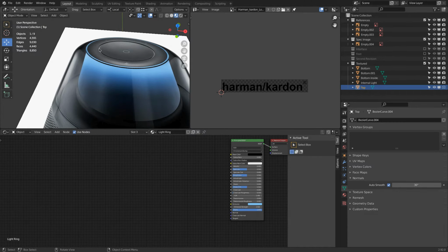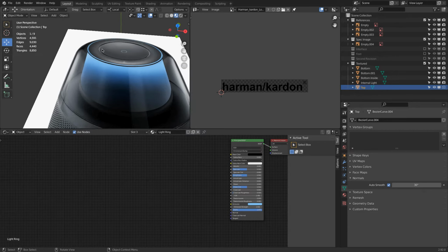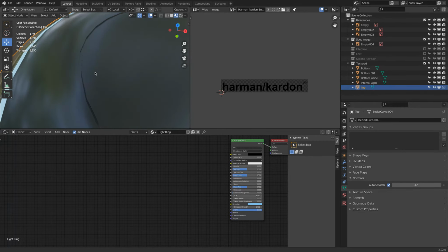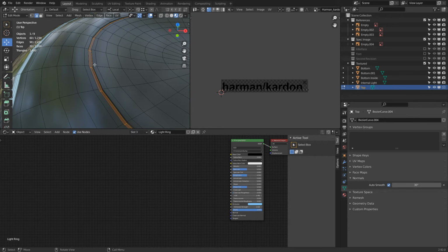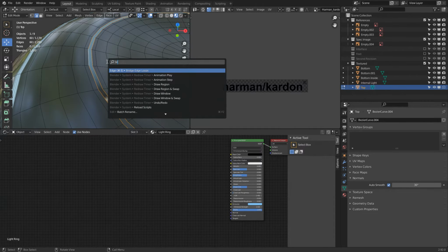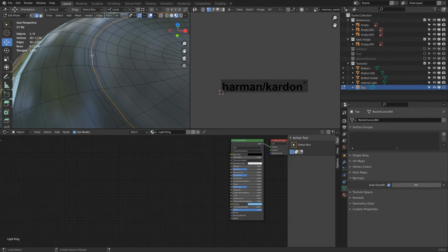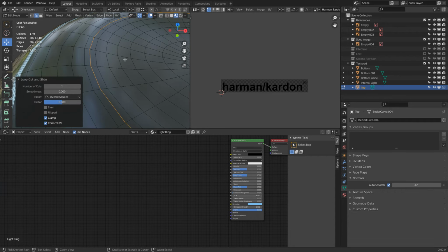Okay, you see it looks like there's some sort of other material behind it. Our gap here actually is way too small. So how do we make this bigger? Easiest thing, we delete this, go to edge select, alt click this, shift alt click this, and then press spacebar, type in bridge. So we bridge it, click this, alt X, dissolve edge, click this, X, dissolve edge, control R at the center, control B, and we just make a new cut.